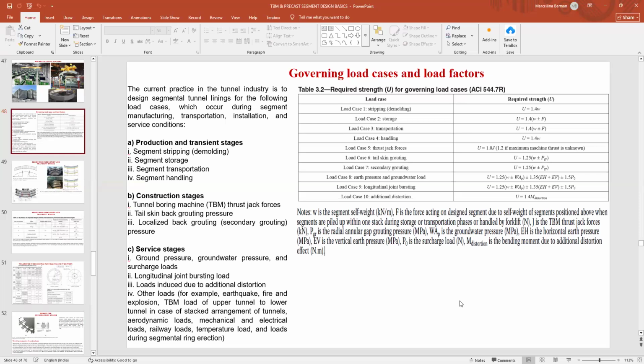There are also other aspects, as I told you earlier, in the bolt pocket where I am getting very less cover. There comes the durability part. I cannot change the reinforcement arrangement because my drawings have already been approved or I have already started my production. So what we did here, we put a plastic sheet there. The plastic sheet takes into account the durability part. So there are alternative arrangements even if you cannot change your reinforcement arrangement or the thickness of the segment.